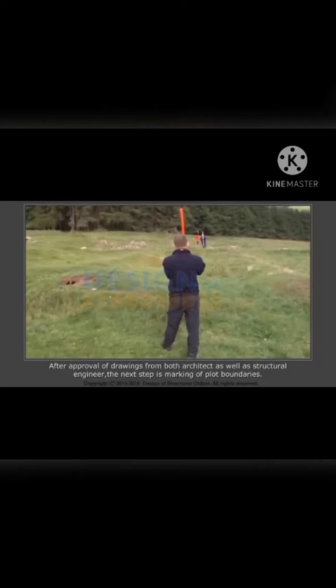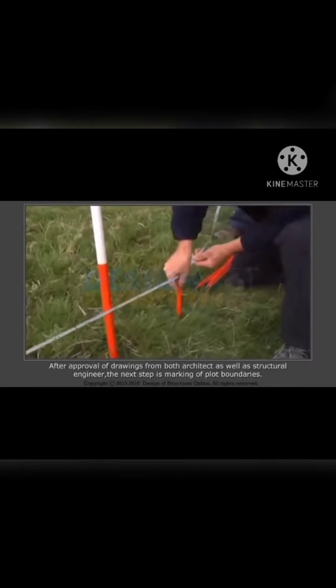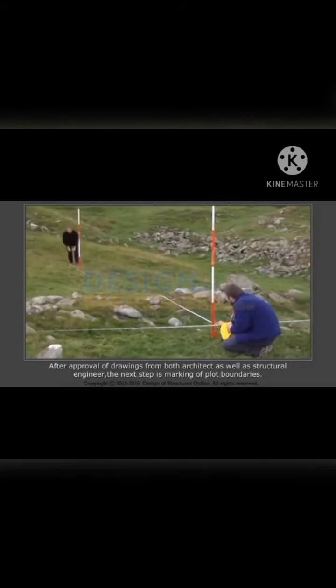Here I will present about the lower structure of the building. Preparation of drawings as per requirements of client. Once drawings are completed, approval of drawings is important. After approval of drawings from both architect as well as structural engineer, the next step is marking of plot boundaries.